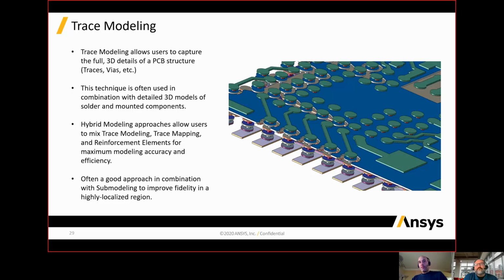A lot of our customers are starting to use stacked vias. So not just regular plated through holes, but they're using either filled vias, like buried, or even plated through vias that are filled, or they're doing stacked versus staggered. On the whole question of stacked versus staggered, there's no question that staggered is better. You sacrifice real estate to get better reliability. We know how to model this. We've been modeling this for years. It's just become more apparent. More people are starting to use this kind of stuff in high reliability applications, which are difficult, and they're looking for yields. So anytime you have those, this is excellent.